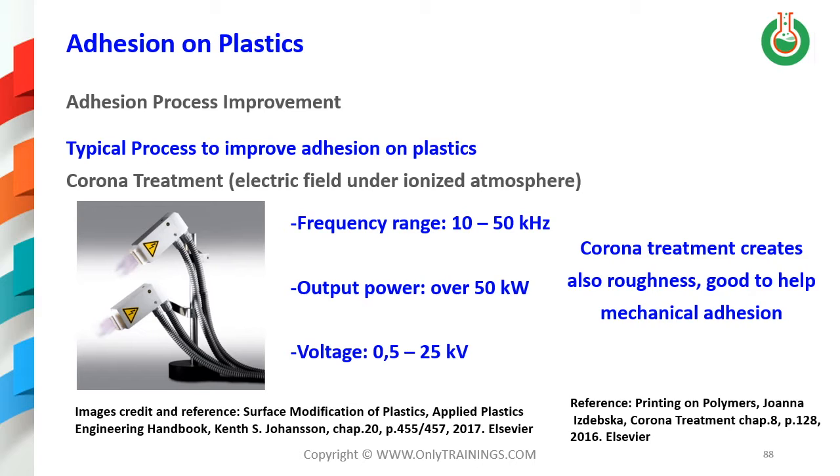Different plastics, films, and materials have different characteristics and different amounts of slip additives, which will determine the effect of the corona treatment. So there are no limits with regard to the materials that can be corona treated. However, the required intensity of the corona treatment may vary significantly.